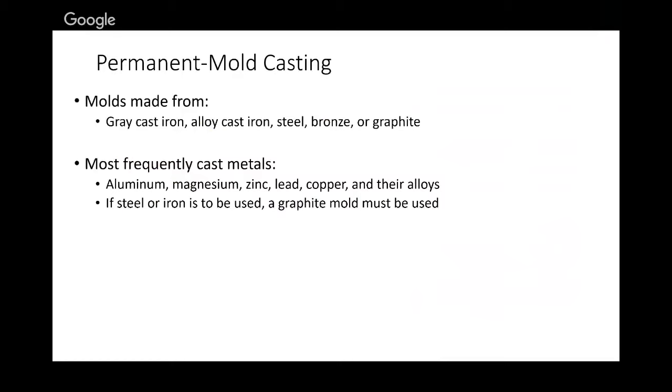Let me talk a little bit now about this permanent mold casting. As you can see, I'm not going to go through and read all this. One of the things I want you to recognize here is the melting temperature, or the comparative melting temperature. Okay, with the sand casting, there's really no limit as far as metals. The quartz melts at a higher temperature than all metals, I guess all. And so there wasn't an issue. Okay, the sand casting works for anything, but what we have here is these permanent molds are made out of metal, right? Well, okay, graphite's not, but they're made out of metal.